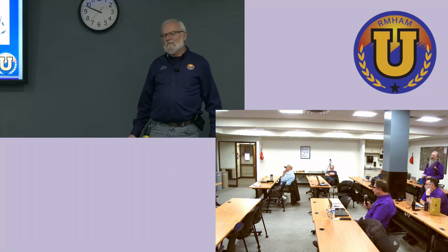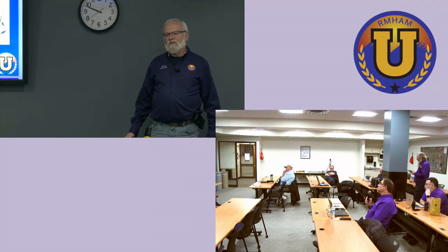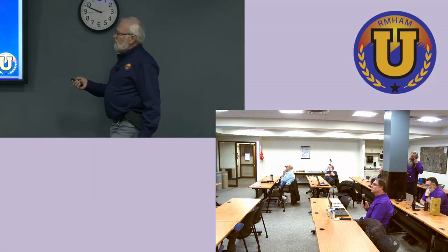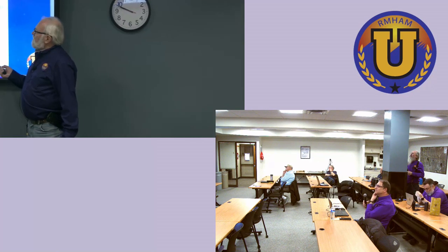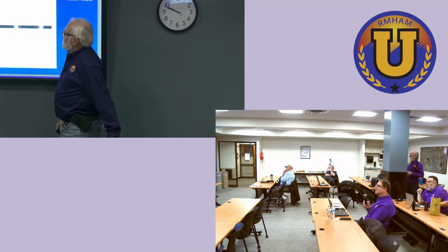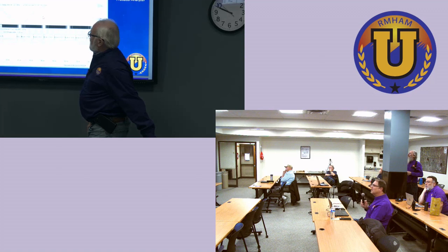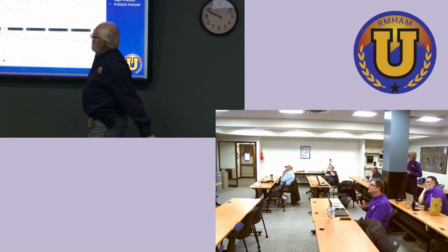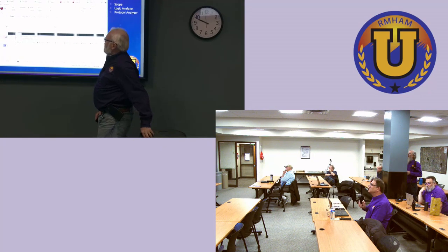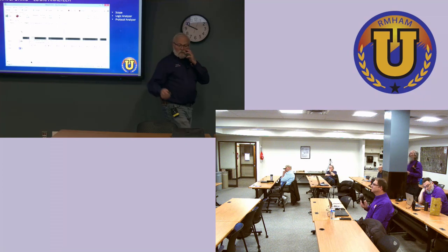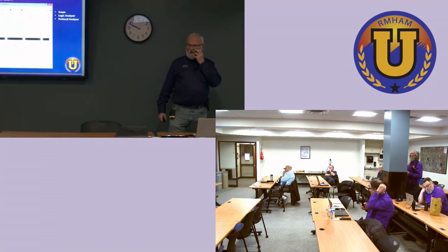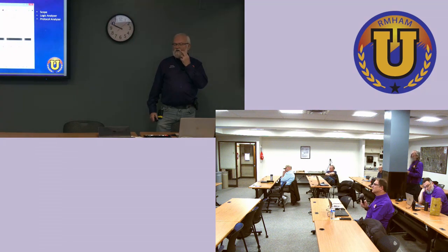Dean? Does a logic analyzer do state analysis, if I provide my own clock? I believe it does. A lot of these are timing only, but I've never looked at this one. It's pretty flexible. I would look in the waveforms manual at the protocol, at the logic analyzer.